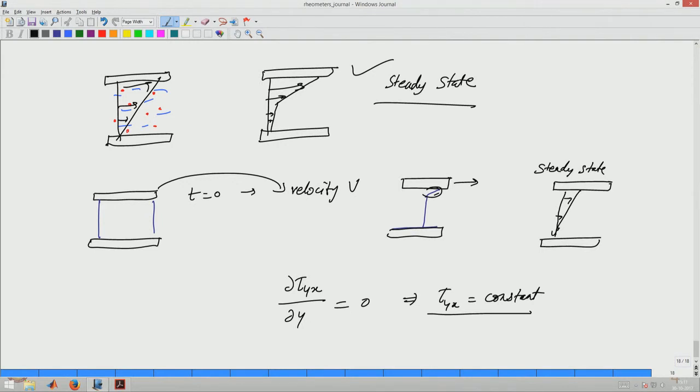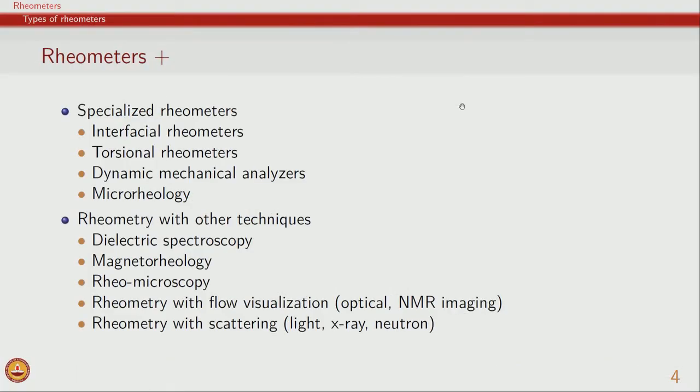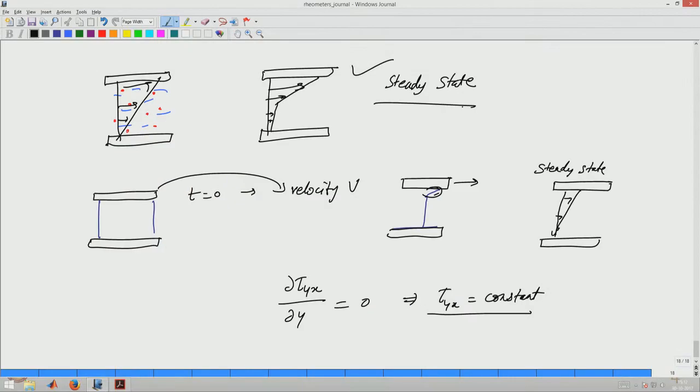So, for examination of shear banding or any such features in rheometric flows, flow visualization is done, and there are multiple ways. What I explained right now was an optical method, where you put in particles, and this technique is called particle image velocimetry, which is basically the measurement of velocity using images of particles.